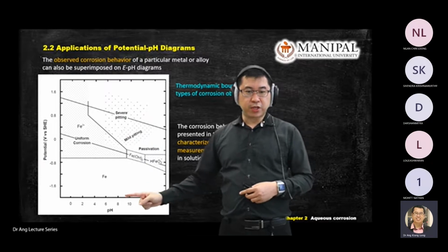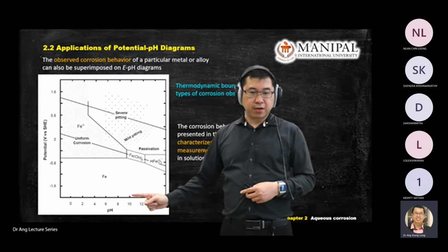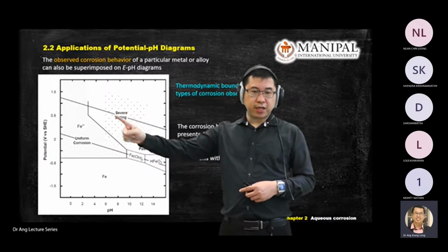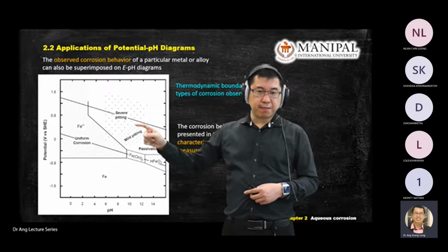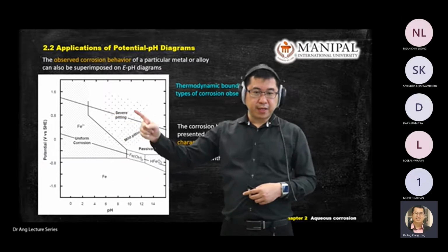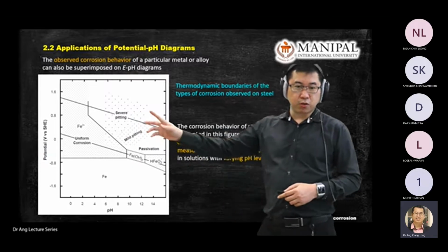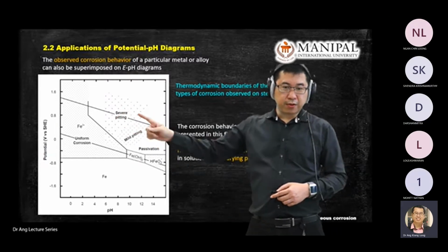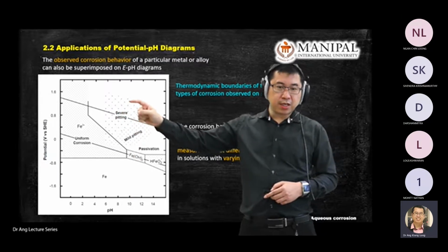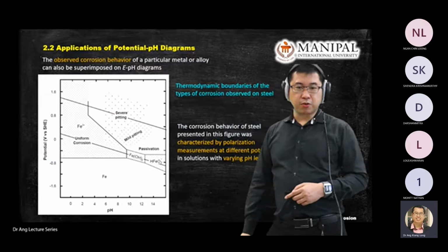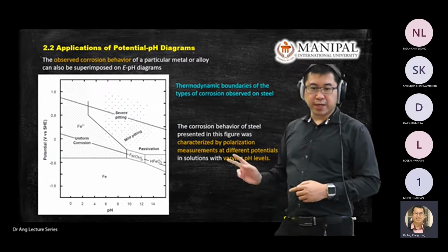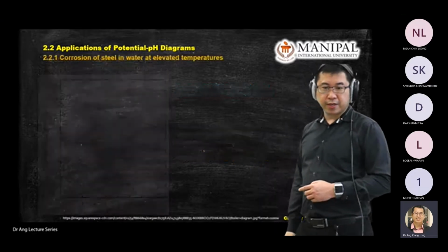However, if you reduce the pH value, maybe to 6, you project up. Over here, you will see the same process happen, but at this point, because of a more acidic environment, we have more serious corrosion. And on this chart, for this particular setting, you will see more serious pitting corrosion happen, right? Okay, so this one you can read.